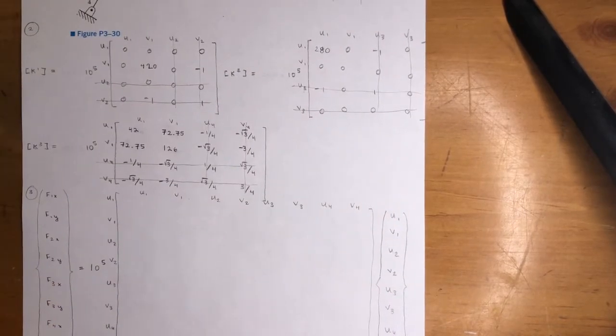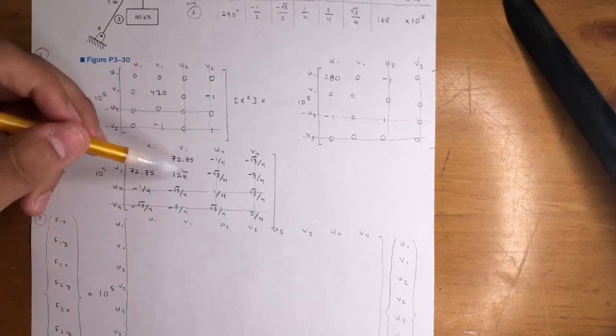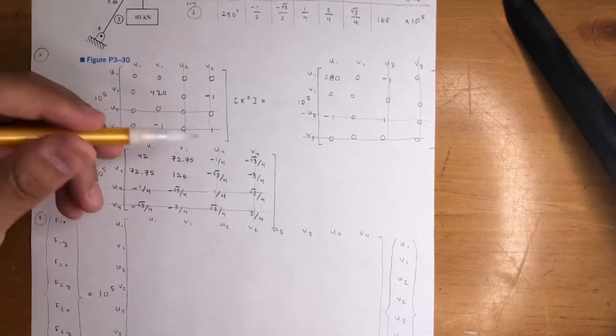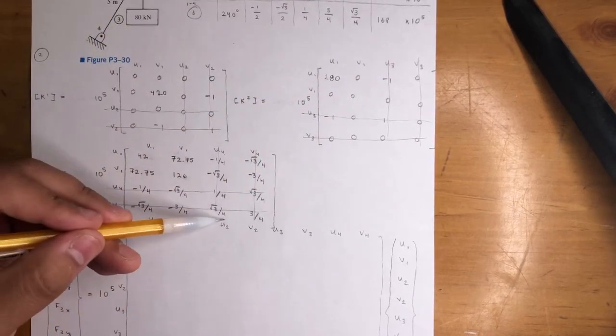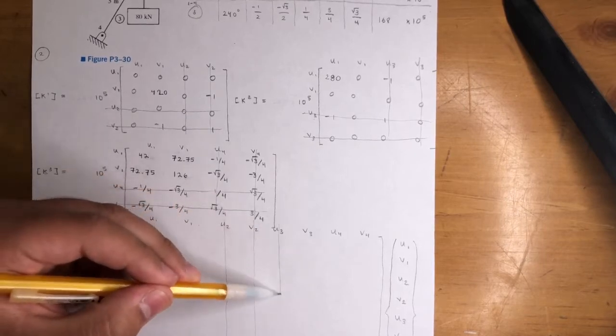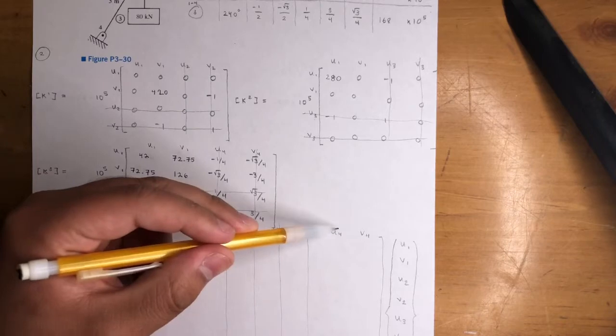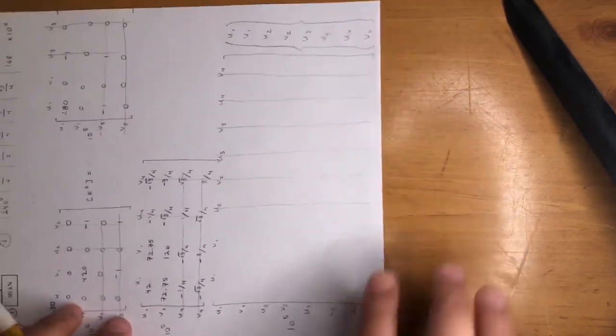All right, cool. So again, just like we did earlier, we're going to apply the boundary conditions. If not, you would have to add the whole matrix. It'll be super crazy. But U2, V2, U3, V3, U4, V4, they're all 0. They're all fixed boundary conditions. So I'm going to go ahead and do that. Cancel all the rows and columns. Let me go this way.